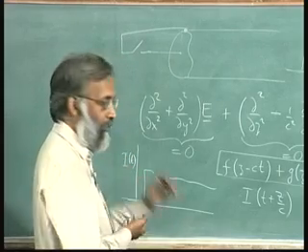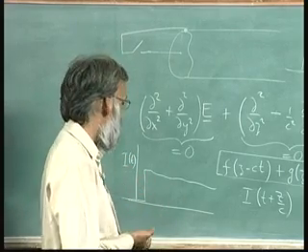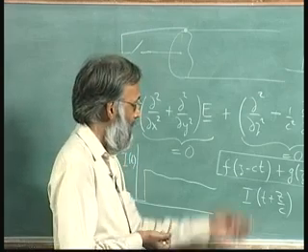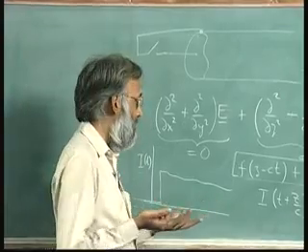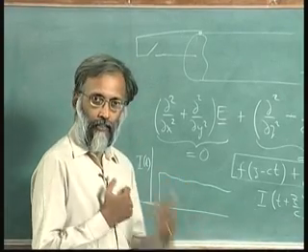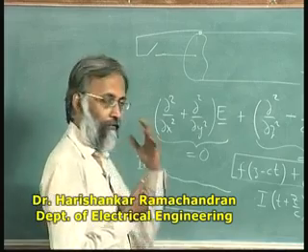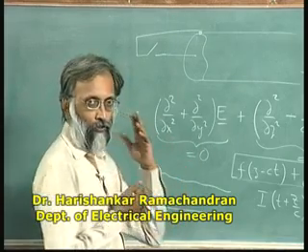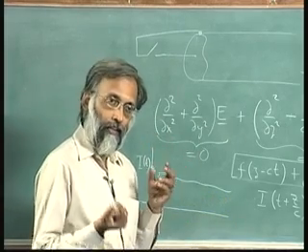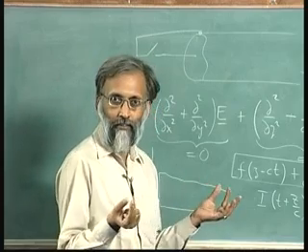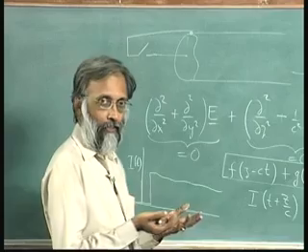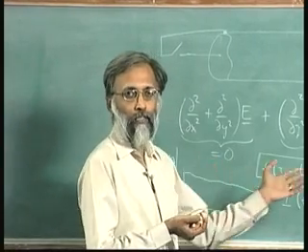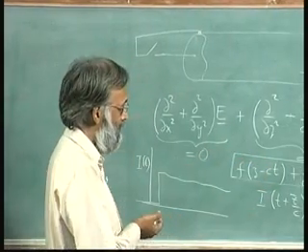Even if the rise time is of the order of nanoseconds, this kind of behavior should happen. So that is why you will see that an oscilloscope has a megahertz rating. Up to that frequency, the oscilloscope can give you signals faithfully, and they will give you cables that you are supposed to use with the oscilloscope, which in fact also carry this information faithfully up to that frequency.